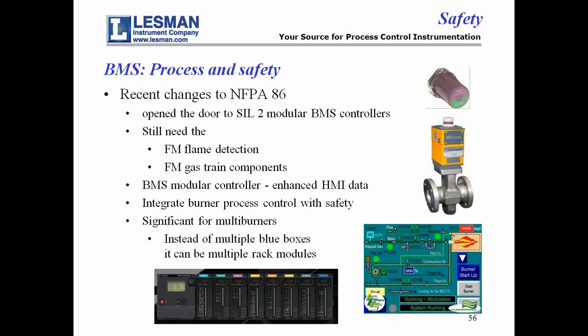The big effect of this actually is that because this now looks like a PAC or PLC and it's got communications on it, you can take the data out and you can put it into an HMI. There's a little example on the side here where you can see all the different components for the gas train and all the stuff that's out there. So this is a huge advance forward to giving you more information so that you can manage the burner train.